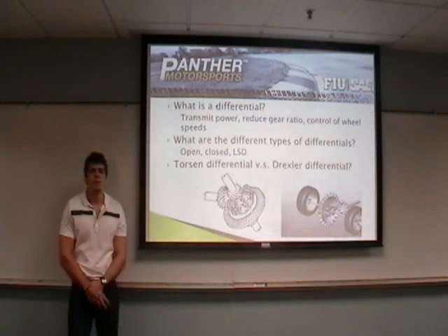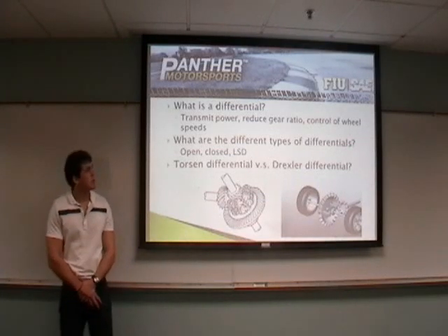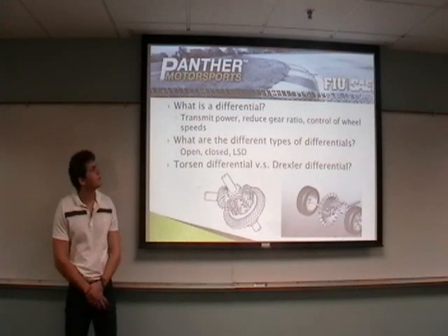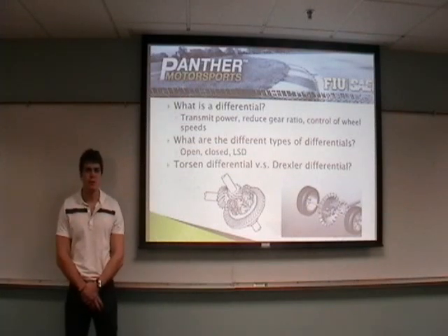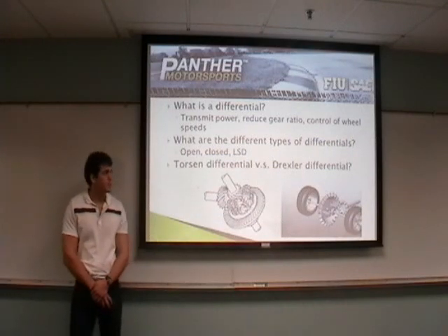What is a differential? A differential serves a couple key purposes. It must transmit the power from the drive shaft to the wheels. It acts as a final reducer in the gear ratio, and it must control the wheel speeds.